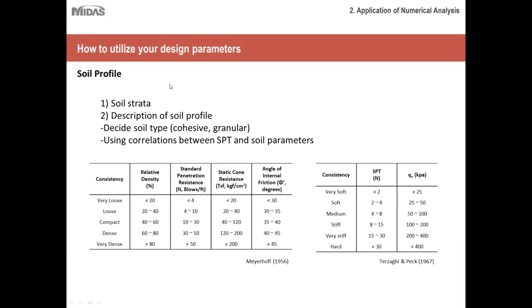Okay, and then make sure to have your soil profile ready as far as your strata, but then also your various parameters. So these should be nothing new to you guys. For example, relative density, your SPT N values, consistencies, internal friction angle, and then also, for example, if you're doing a seepage analysis, you need your permeability coefficients. So just make sure to have all of this data ready so that you can input it into the program.